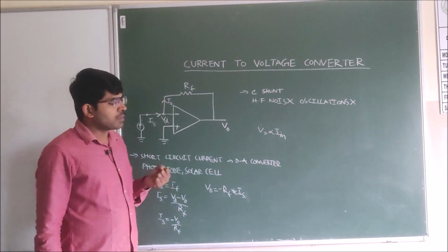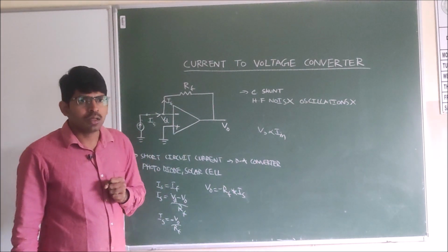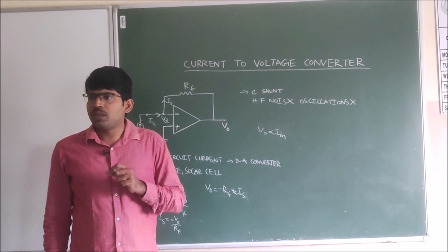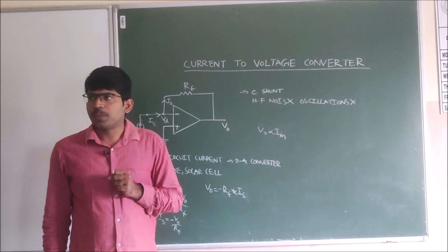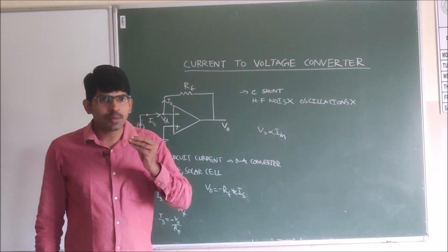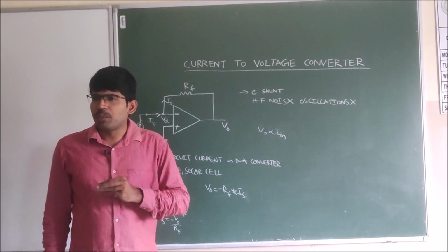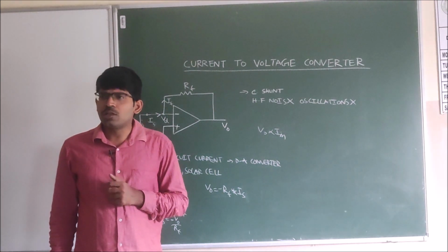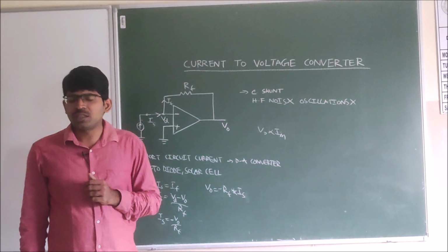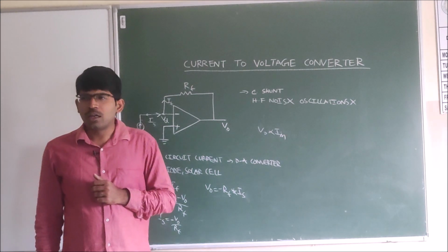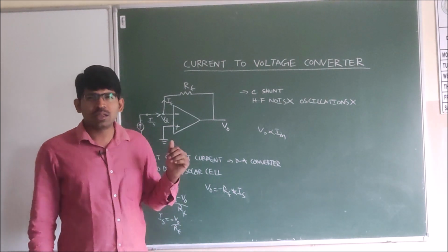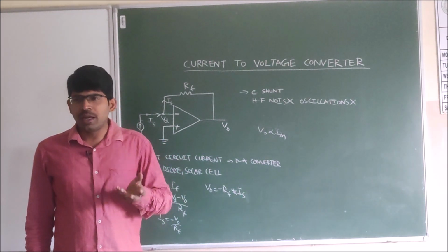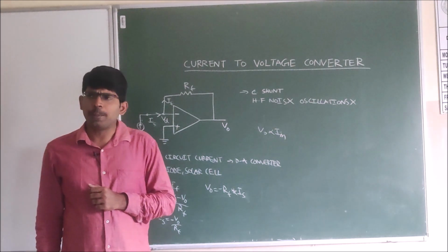Also, sometimes when we take solar cells, photovoltaic cells or photodiodes, in these components the current will be very small. Our meters might not be able to detect such a small current. Even if they detect it, the current will sometimes fluctuate. We might not get the perfect current because the current of these devices depends upon the light, so based on the light, the current is changing continuously.